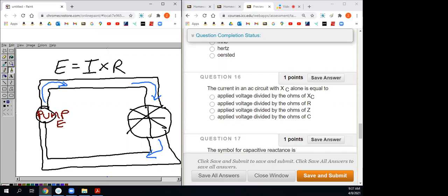You have a certain resistance value from you to the earth, correct? To get current to flow through your body, a certain voltage or a certain force has to exist. So between me and the earth, 120 volts going into my head is probably going to get a little bit of current flow to the ground, right? What if I put 480 up there? Current's going to be higher, right? That's where things become dangerous.